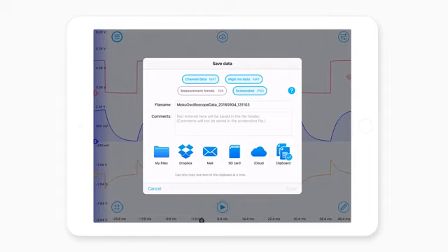So one thing that is really, really useful here is if you don't want to save your file in a particular format, you can just switch it by tapping on the file format label on the right-hand side. So I might save my channel data as a MATLAB workspace file, and I might save my high-resolution data as a CSV, comma-separated variable file.